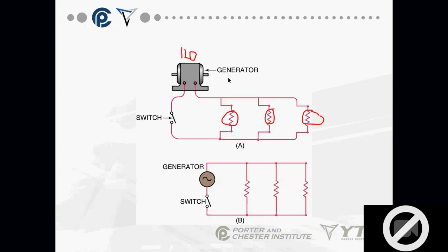My total amperage in the parallel circuit is the amperage of this, the amperage of this, and the amperage of this. Again, I want you to think back to your houses. Your total amperage that comes out of your breaker panel is every room added together. In most residences, you have a 200 amp circuit. You have 200 amps in most of the newer residences.